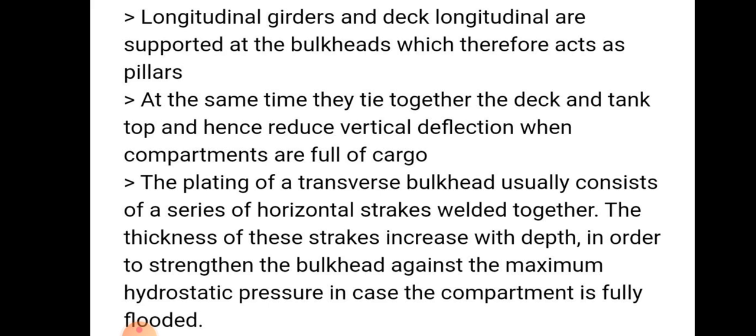Longitudinal girders and deck longitudinals are the supporters at the bulkhead, which therefore act as pillars. At the same time, they tie together the deck and the tank top, and hence reduce vertical deflection when compartments are full of cargo.